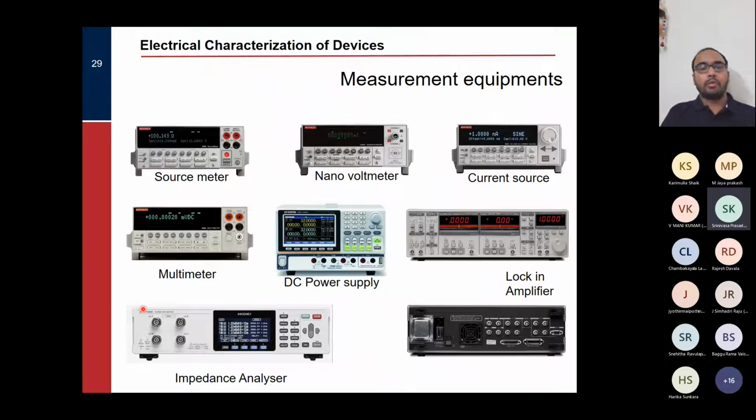So now the question comes. We have discussed the methods, but how do we measure? In, let's say, undergraduate labs, we have these analog meters, right? They can help us measure up to, let's say, microampere current. But as you know, those meters are not very accurate, specifically when you're talking about nanoscale systems, where the current could be very low, like nanoampere or picoampere, 10 to the minus 12 ampere, even femtoampere.